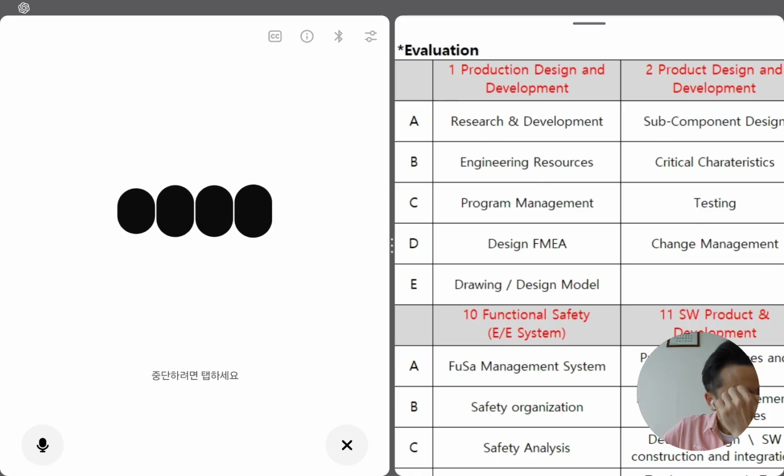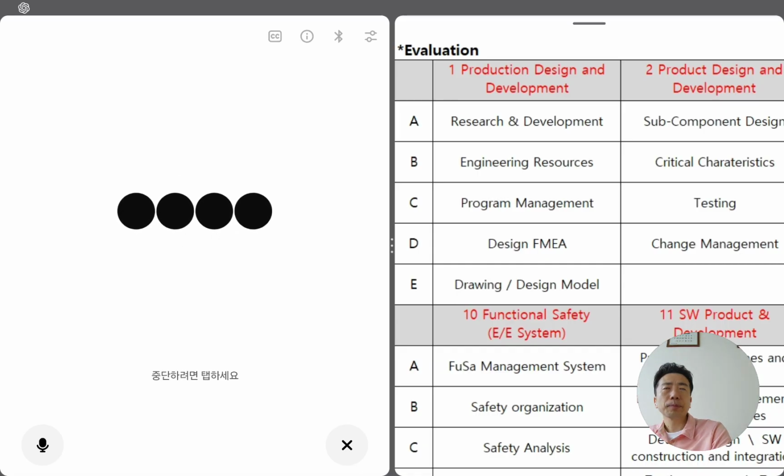Perfect, David. You repeated it really well and you're building that mouth memory. Here's the polished version, step by step, exactly as you want to keep it in memory. Refined version. As far as I understand, the design FMEA should be like a placeholder. It should contain every potential risk and failure mode. If we get a customer complaint or a field failure, the root cause should be included in the DFMEA. If the DFMEA is done well, it should already cover those potential risks and failure modes. That way, even if a product fails in the field, the cause must already be in the DFMEA, if the DFMEA is done well.